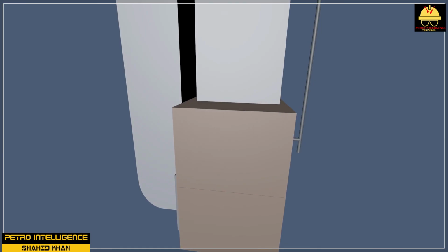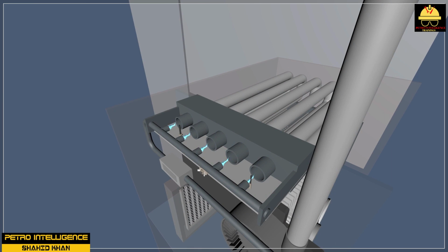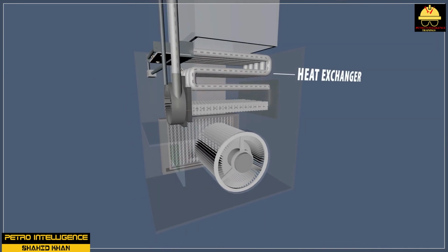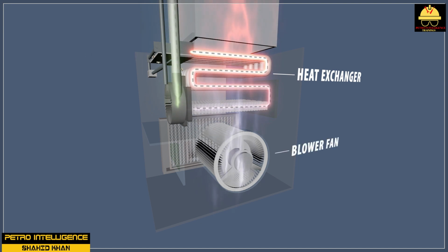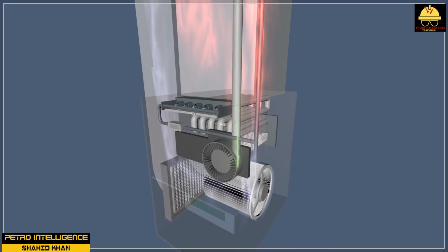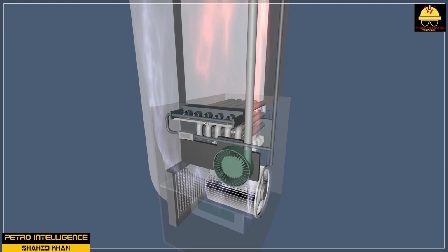Furnace applications and theory of operation. A furnace, that is, a fired heater, is a device used to heat up chemicals or chemical mixtures. Fired heaters transfer heat generated by the combustion of natural gas, ethane, propane, or fuel oil. Furnaces consist essentially of a battery of pipes or tubes that pass through a firebox. These tubes run along the inside walls and roof of a furnace. The heat released by the burners is transferred through the tubes and into the process fluid.